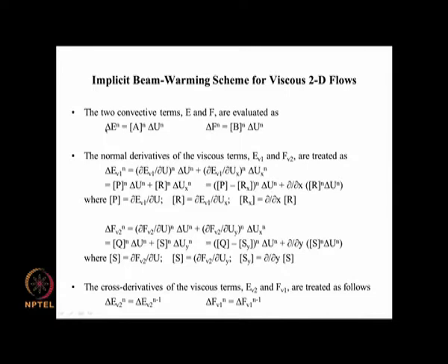So it is a rewriting of these nonlinear and coupled terms in this way, where the primary variable ui n plus 1 is coming out unscathed in an implicit form, but the coupled coefficients and the nonlinear coefficients are evaluated based on the previous time step values, which we know. So this enables us to take account of nonlinearity and coupling, and this is done for different terms, the convective terms and the viscous terms, in different ways, and that is what is summarized here.